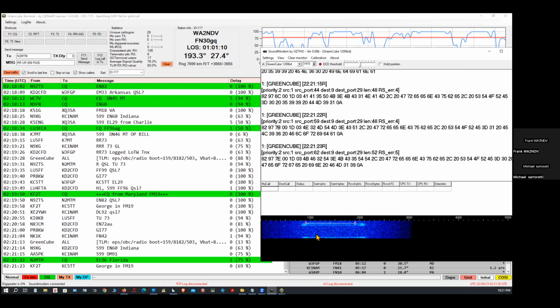So if you're using the SAT tracker, you can adjust your frequencies and save the frequencies as I have done, and maybe make a slight correction with the VFO if necessary. But whatever radio or whatever tracking software you're using, this is how the waterfall should look, and you'll be successful.